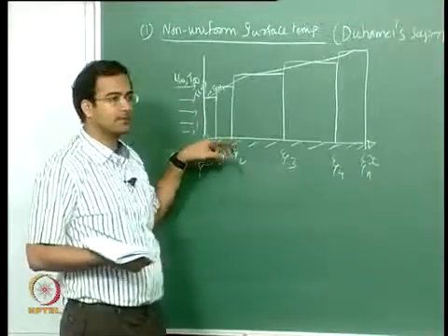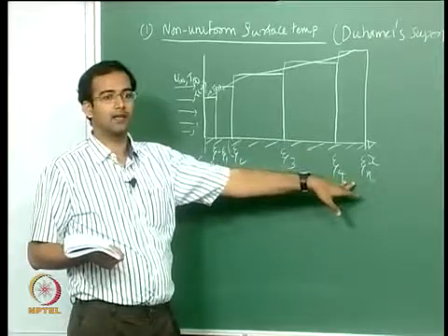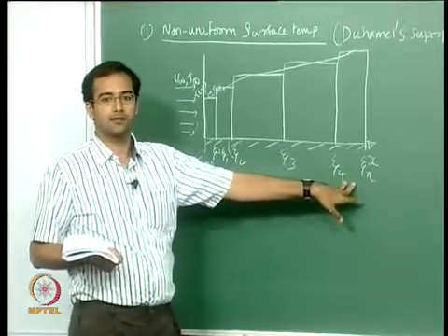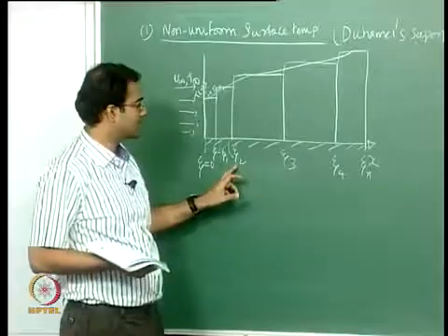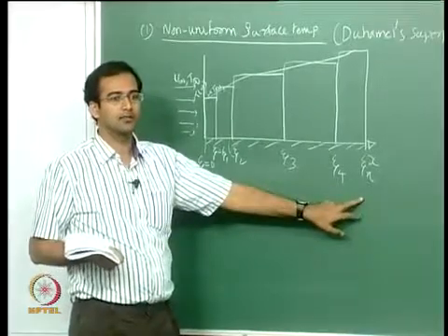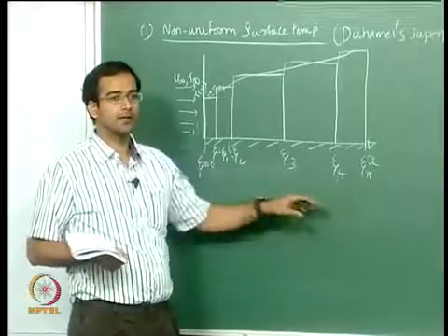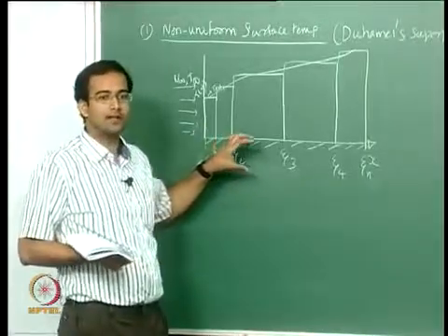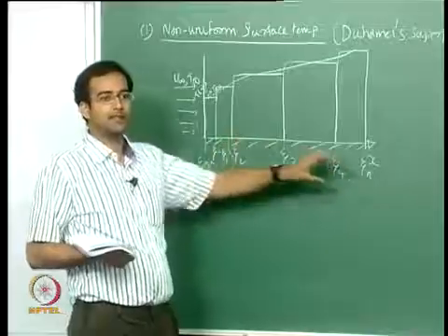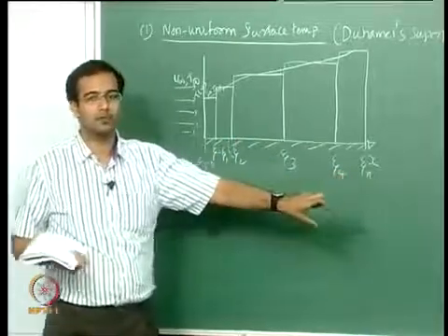That is applied to the entire plate, and again you know the solution for that. And from zeta equal to zeta 2 till the end, you have T wall 3 minus T wall 2. Like that you keep on applying successive deltas as your boundary condition and you solve the problem.